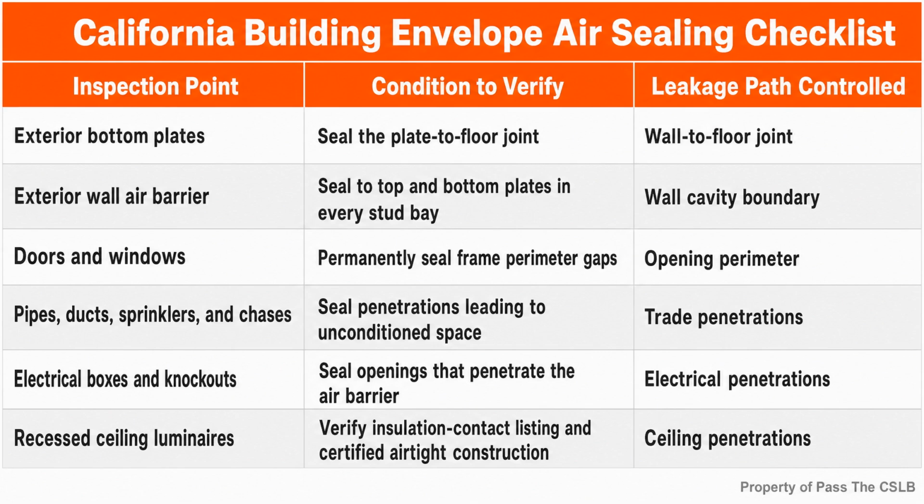Electrical boxes that penetrate that barrier also need to be sealed. Doors and windows create perimeter joints. Cantilevered floors create assembly transitions. Pipes, ducts, fire sprinkler lines, whole house fans, chases, wiring, and electrical knockouts create trade penetrations. Each location is a reminder that the envelope is a continuous system, even though separate crews build it.